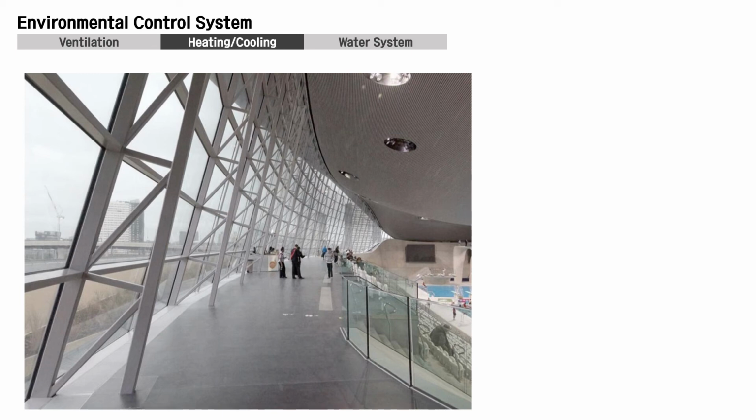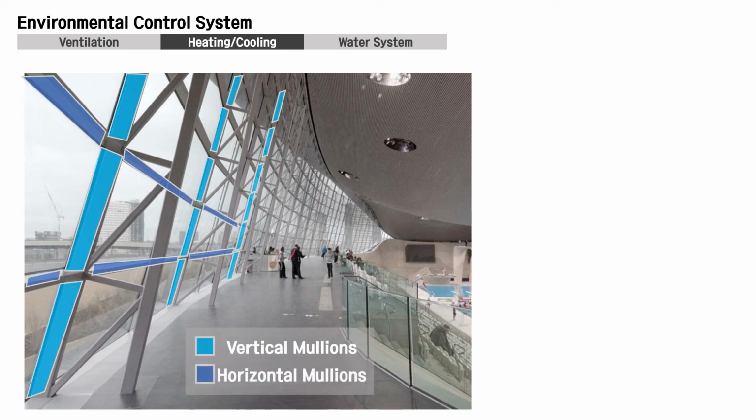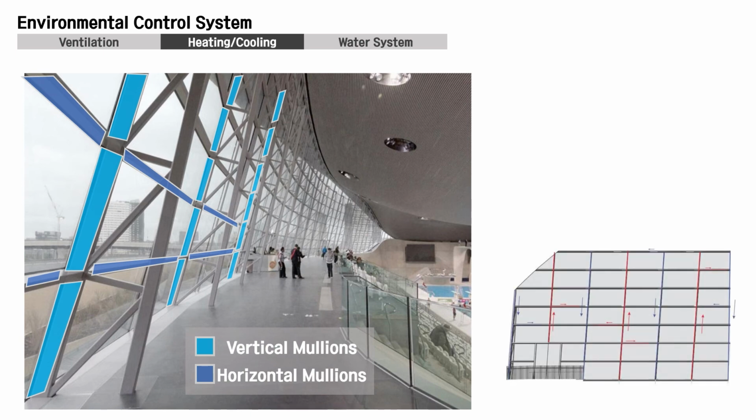Detailing the facade, the curtain wall was carefully considered both from a structural standpoint and a heating and cooling standpoint. The expansive curtain wall had to be self-supported, so a series of enlarged vertical and horizontal mullions attached to steel trusses was implemented, and the heating tubes, which are filled with a water-based solution, are supplied from a mechanical filtration room.